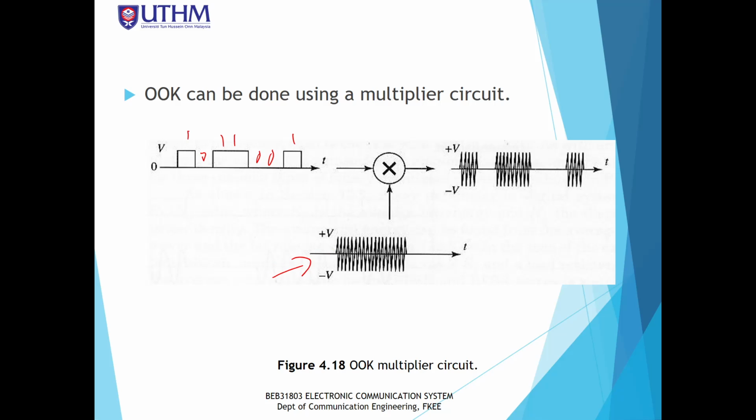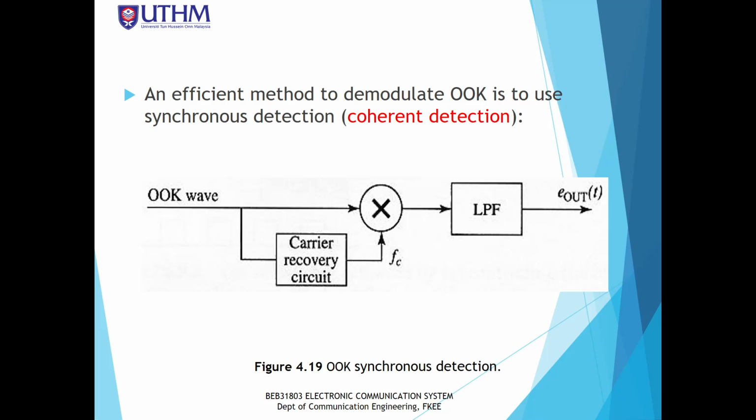So you see that here is on, off, on, off, on and so on. So there is signal, no signal, signal, off and so on. So this is the ASK, or OOK. So this is signal generation at the transmitter. Okay, this happens at the transmitter side. Okay, how to generate the ASK signal.